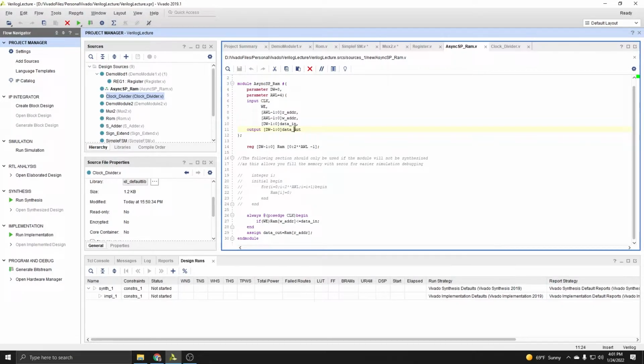The textbook has things, for example, the register file, which is just a dual port RAM, that has specific names for the ports. For example, its enable signal is not just write enable, it's register file write enable, RFWE. And the two read addresses are RFRA, register file read address 1, register file read address 2. And then you have the register file write address, RFWA, and register file write data, RFWD.